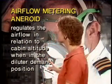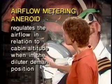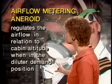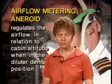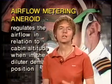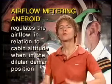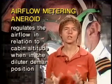Bunch of words there. What exactly does it mean? A mask like this can be set for either normal, what they call the diluter demand position, or it can be set for 100% oxygen. Most of the time, at most altitudes, you do not need 100% oxygen in order to have adequate oxygen because there is a certain amount of oxygen in the air.